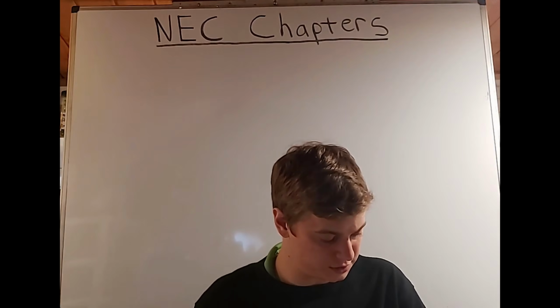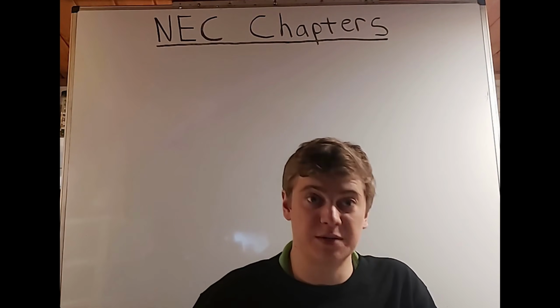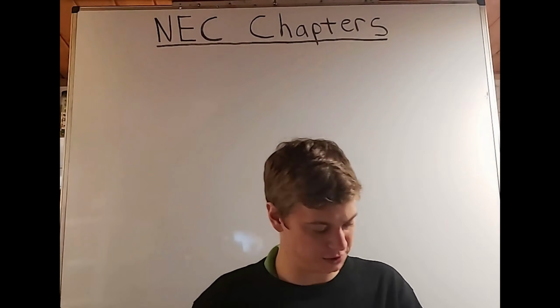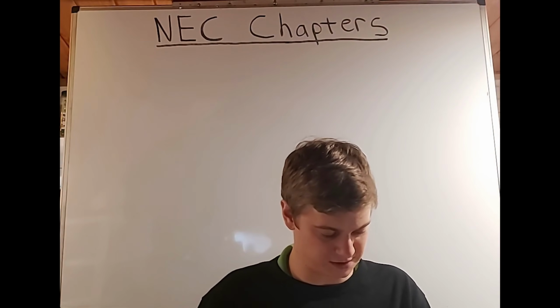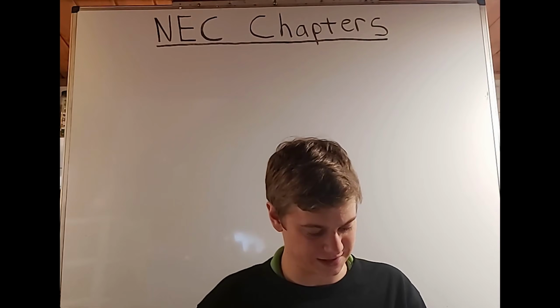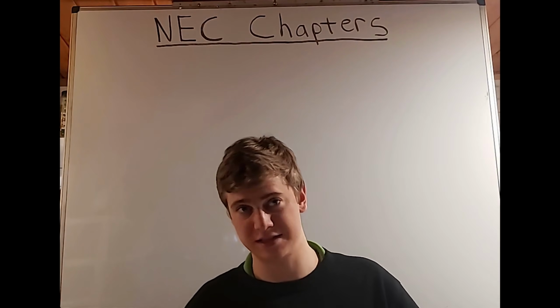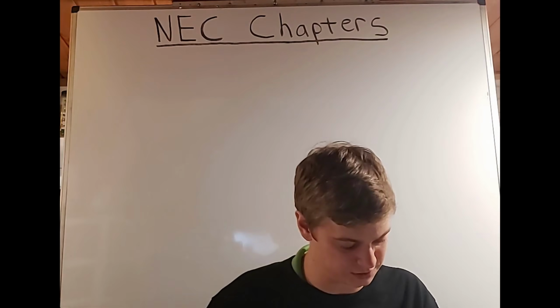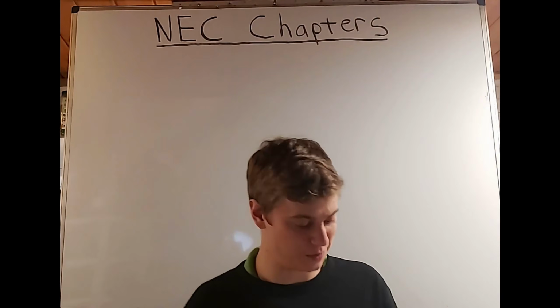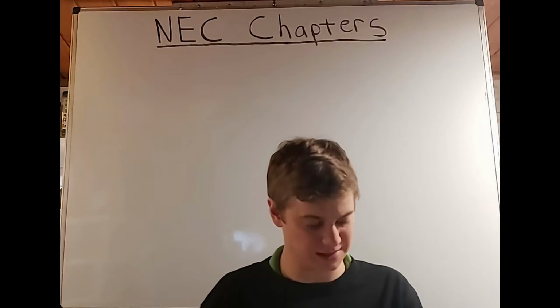Okay, moving on to article 110.32, working space about equipment. We'll see it basically talks about what I was mentioning earlier, where we see energized parts that are exposed have the minimum clear working space not less than 6.5 feet high, 3.5 feet wide, or the height/width of the equipment, whichever one is greater. And we'll see it mentions that energized parts that are exposed have the minimum clear working space not less than 6 feet high.